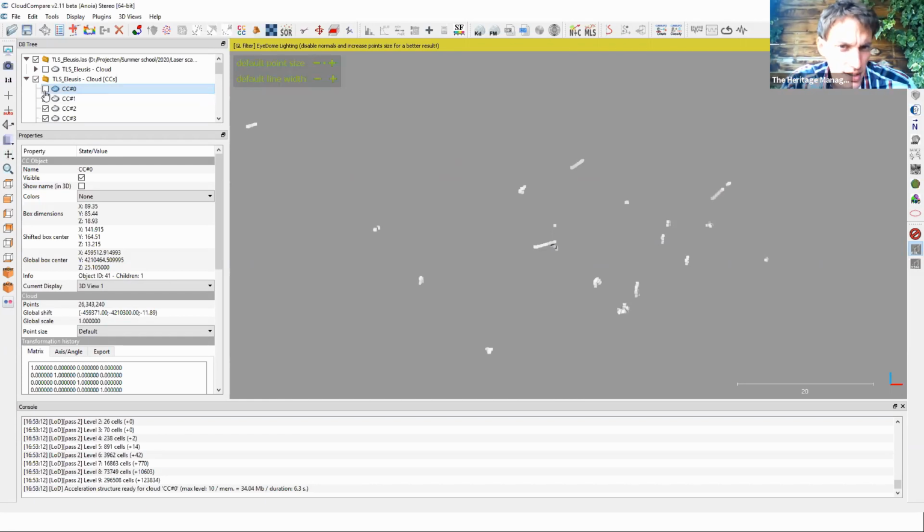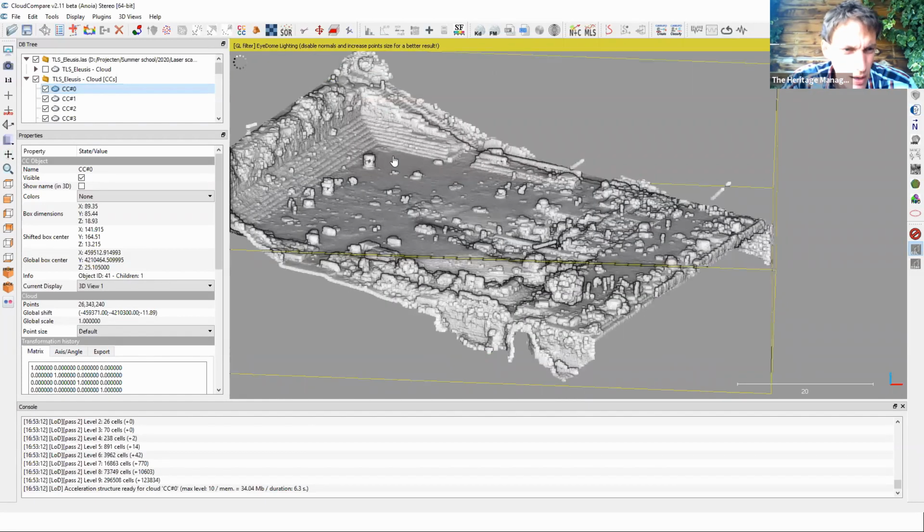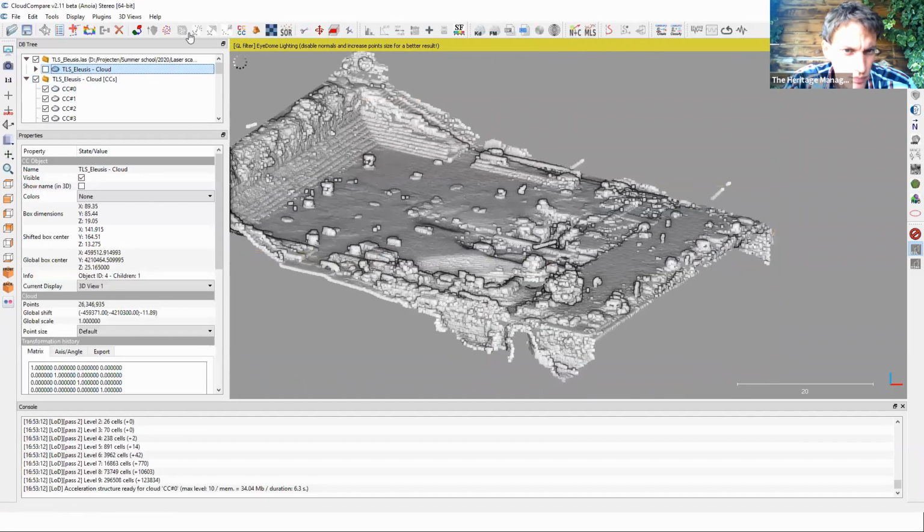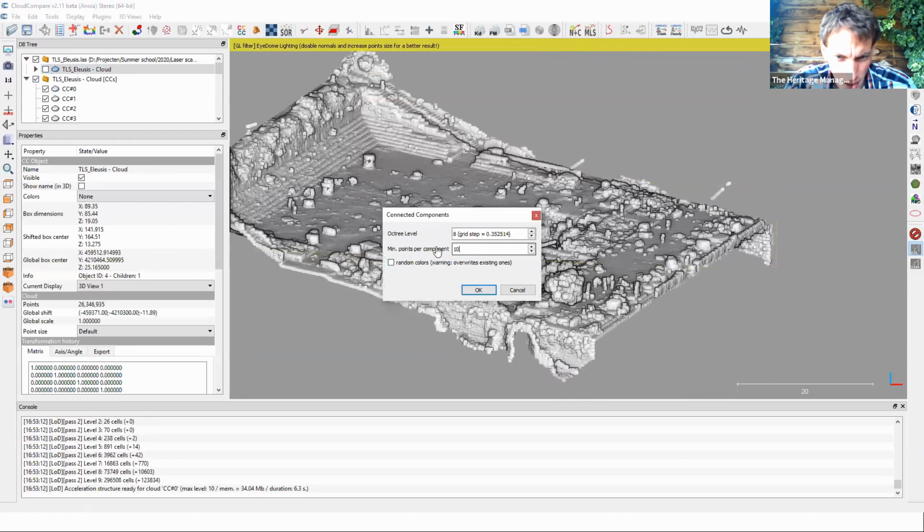A very good question in this case would be, okay, what is then the relevance of this threshold value, the value that I pointed out here? Well, this value will also tell you if there are clusters detected in the point cloud that are further away from another cluster than this threshold and the octree level. And if the number of points is less than, in this case, 10 or 5 or 25 or 50, all these clusters will be eliminated and all these points will be eliminated.